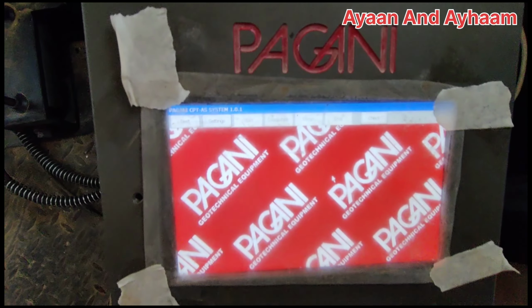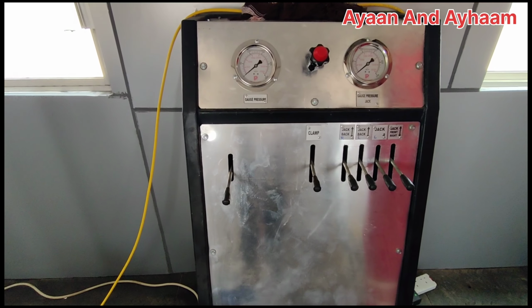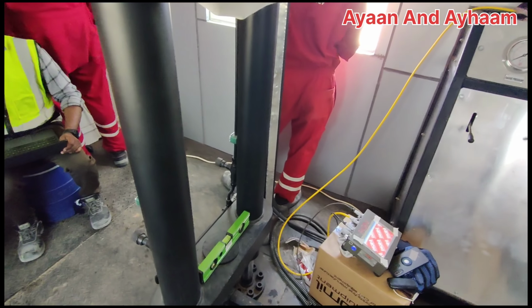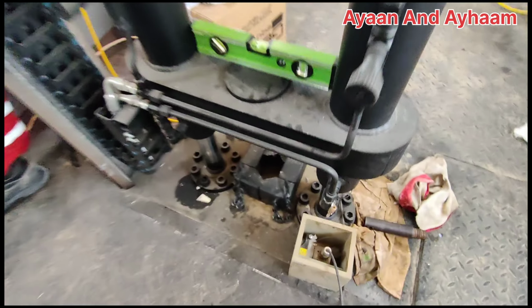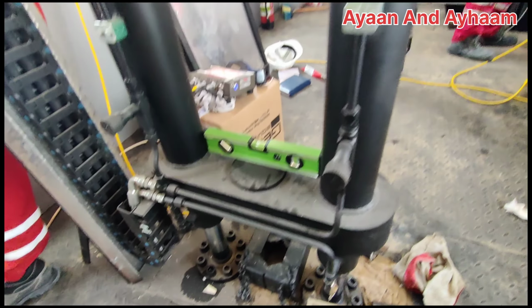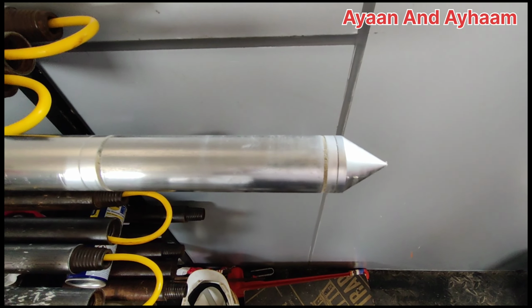In this machine we are entering the data such as point ID, coordinates and its level. This is the hydraulic jack machine to give the pressure to the CPT rod and to level the CPT machine, as you can see. And this pressure plate, you have to level it. I will show you all the procedure step by step.